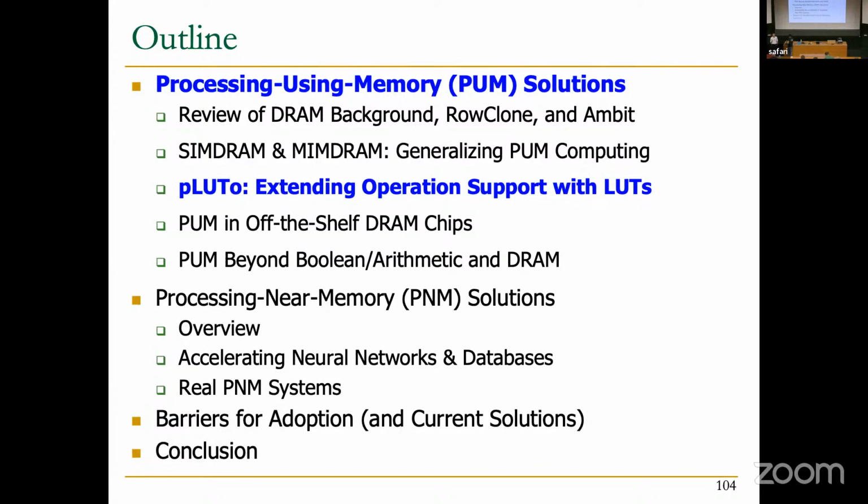Not exactly what you mentioned. I'm going to try to remember exactly what you said, because this is actually a good research thing to check. But what we actually did is some work where we tried to figure out, if you put the DRAM as one of the entities for MOESI or MESI, as part of the coherence tree, what would be the overheads on top of the processing-in-memory computation itself.